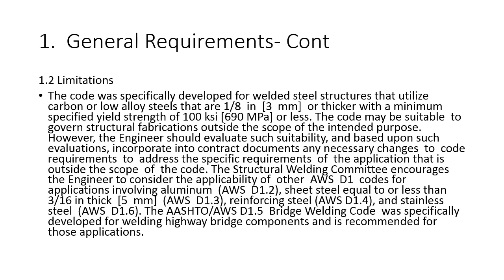If you're building a bridge, you shouldn't use it. If you're using aluminum, this one doesn't work. Sheet steel, equal or less than 3/16 of an inch, you should use D1.3. If you're doing reinforcing steel in concrete, use D1.4. And if you're using stainless steel, use D1.6. D1.5 is for bridges.